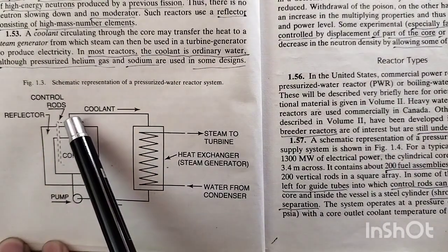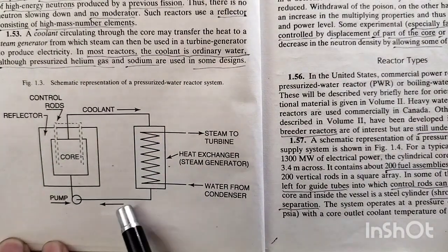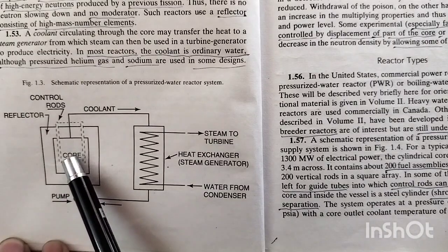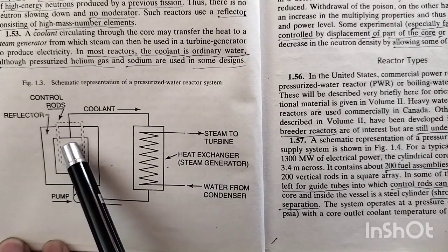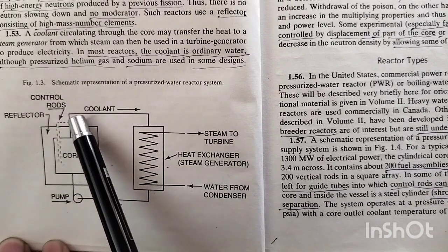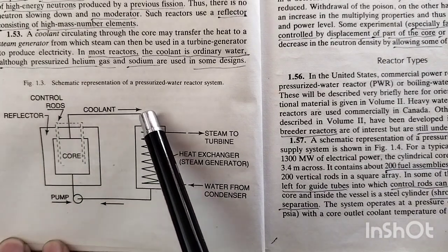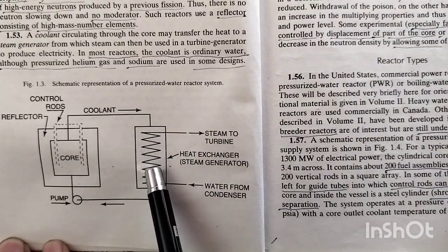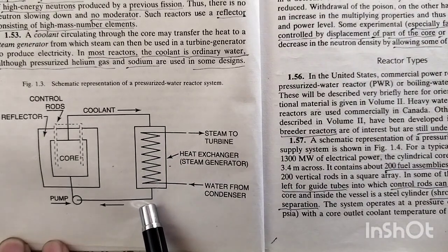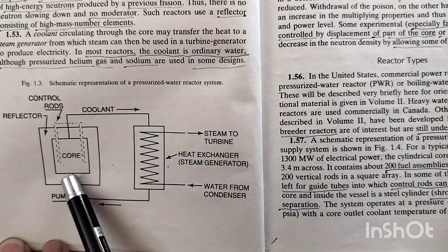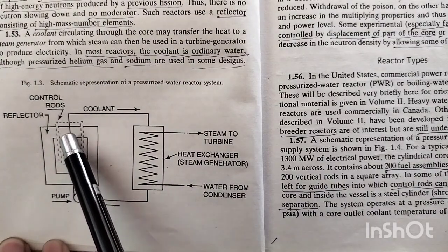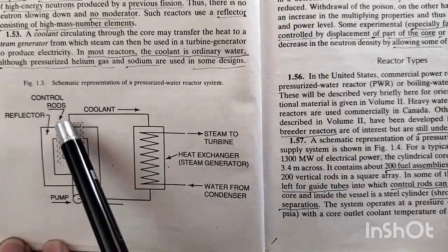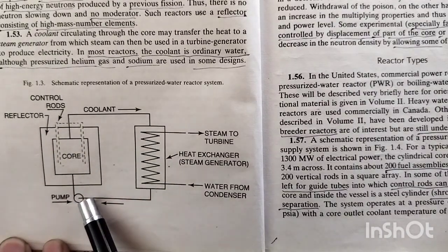And this hot water coming out, cold water going inside the reactor, passing through the fuel bundles or fuel assemblies, and that water becomes very hot. That hot water is going to a steam generator and it will reject the heat in the steam generator, becomes cold, and cold water again enters the reactor core and again comes back. It is a cyclic loop. It happens continuously because of this pump.